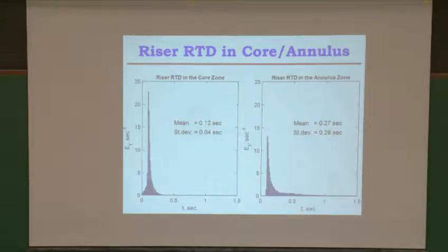We know that this physically makes sense because as the solids are carried upward in the core region, the solids exchange with the solids at the wall that are tumbling down on the core. That exchange, of course, adds to the back mixing of the system and affects the mean residence time, because particles are spending more time in the system.